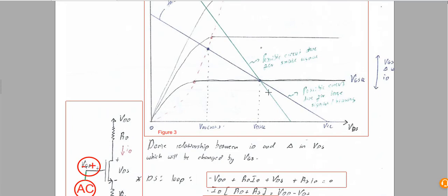and it also shows us the characteristics of the transistor and our VGS and ID relationship. But at this moment, we're going to look at the DC bias. This just means that our DC is biased at this point, meaning our VDS DC is at this point, and also at that current. And from there, we have a specific VG. Now, when we shake VG like that, this thing will stay in saturation and will remain almost linear and will change ID almost linearly.